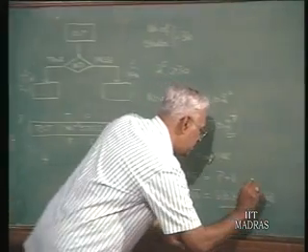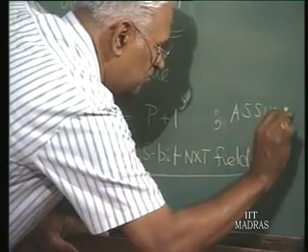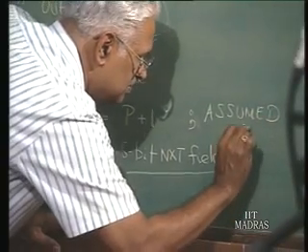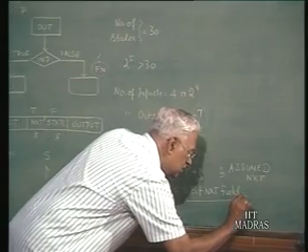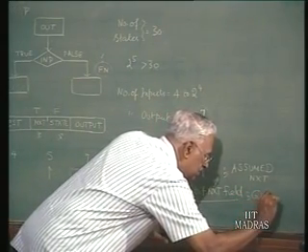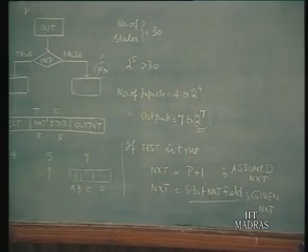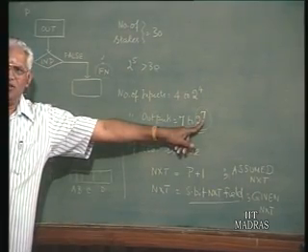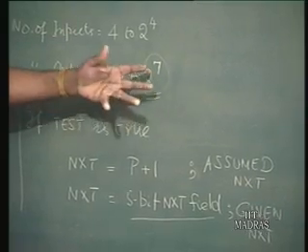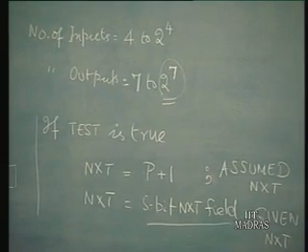So, this particular one is the assumed next state address, assumed to be the present one plus 1, whereas this particular one is the given next state in the micro word itself. And another important thing is about when you can go for linear select and when you cannot really go in for. It will be meaningless to generate only one output at a time.